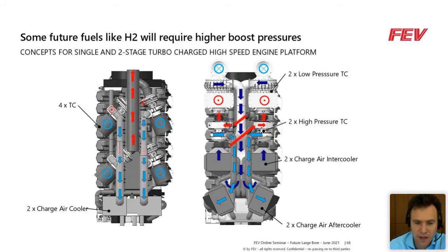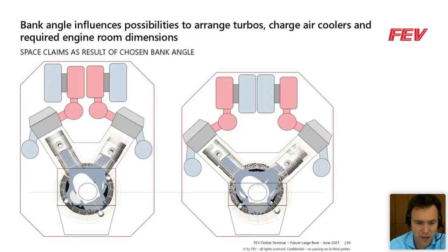And what is the discussion here at the end? It's very well known that when we start to design a new high-speed engine, there is always the question: what is the best V angle? Is it a V90, V60? Of course there is not a right or wrong solution, but this depends a lot on the customer requirements and the application that the engine has to be used for. But of course, since the boosting requirement will be even higher in future for some fuels,